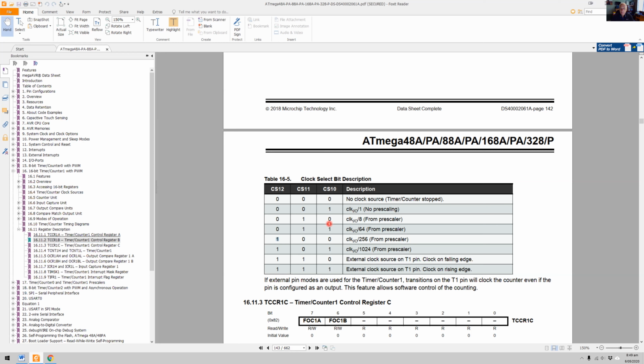So in any data sheet from any microcontroller, you want to start looking for these sort of features. How do we control the clock source, and what are the different options? So we're looking at setting CS, clock source for timer 1, bit 2 to 1, and we'll leave these at 0. So let's go back to our code and just see if we've got that.